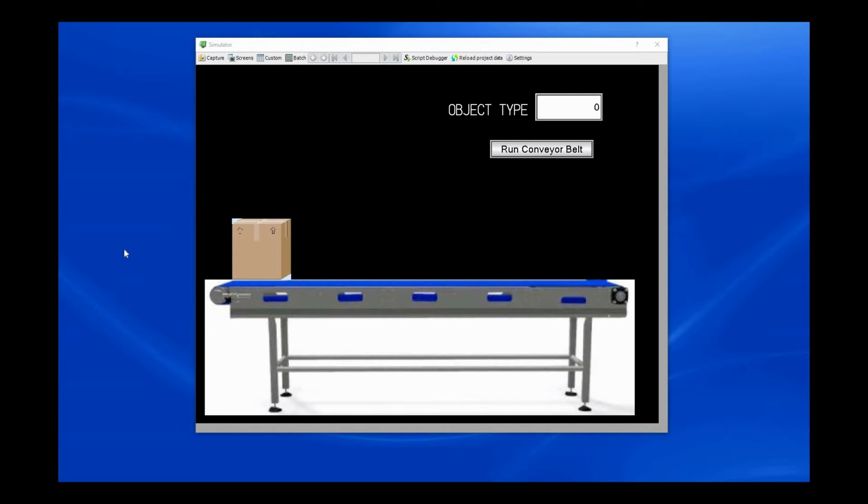In today's tutorial, we're going to see how to use dynamic coordinate and dynamic rotational angle to create animation or moving an object on IDEC HG touchscreen. So previously we have one tutorial using multi-state lamp to create a similar thing, to create a moving object or animation. Okay, so this tutorial will be using another type of method.